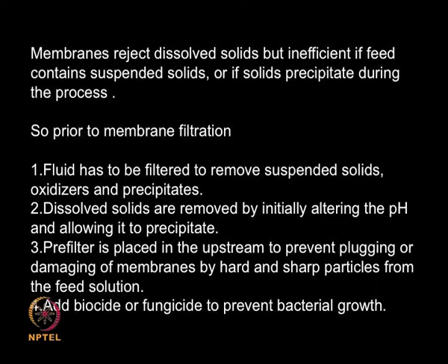Then we can add a biocide or a fungicide so that you prevent bacterial growth. So all these various operations you can perform before you take your solution for membrane operation. So you see that doing a membrane operation is not straightforward, you may have to resort to quite a lot of pre-processing.